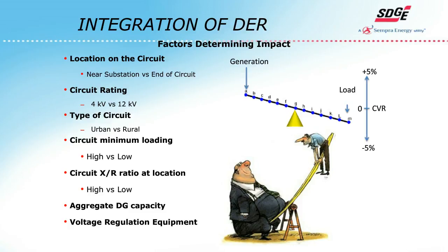To do that, in our particular case, we had load tap changers in the substation, as well as line capacitors and line regulators when we needed them. All of those have controls, and those controls originally were for unidirectional power flow from the substation to the loads. Increasingly, we're having to go back and modernize and retrofit a lot of those controls. There is some additional maintenance associated with doing this.